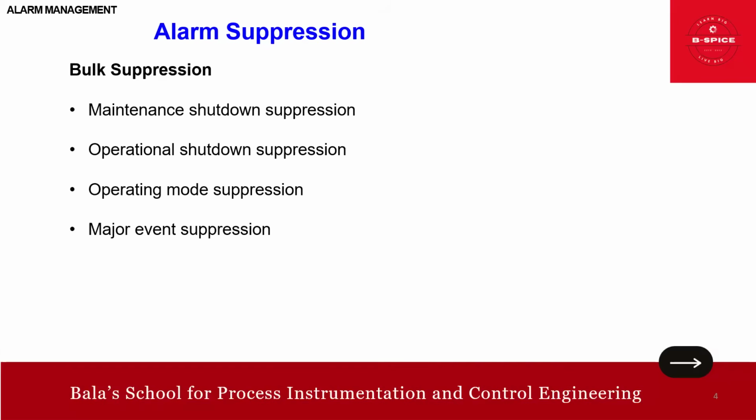For example, in a nuclear reactor during normal operation, an alarm may be required if any rod becomes fully inserted into the reactor. After a trip, an alarm indicating that a control rod has not been fully inserted will be far more important, right?